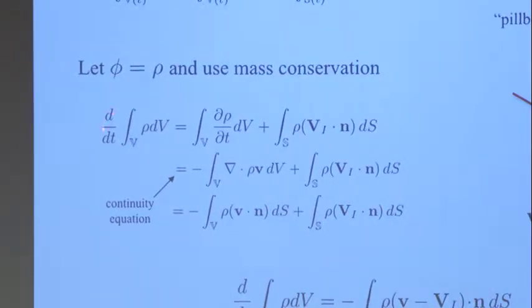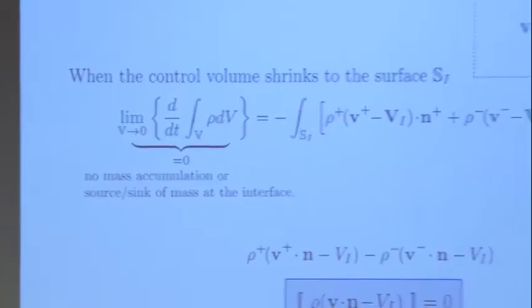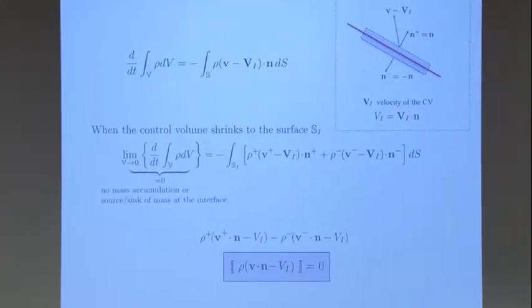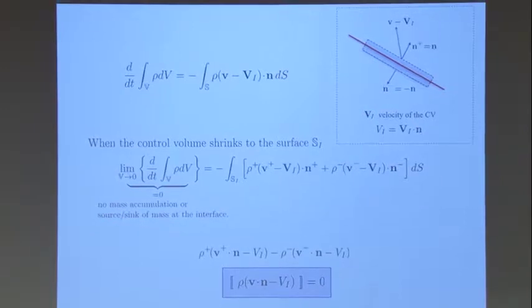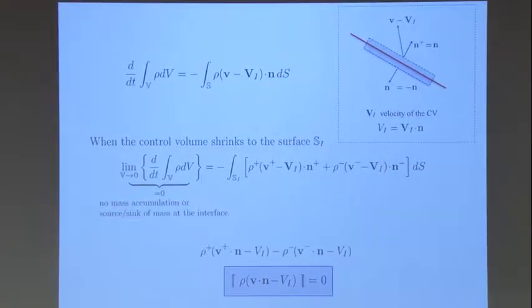And so the left-hand side, which is the time rate of change of the mass of this volume, is equal to this surface integral. Since this is what's written on top here, right? So far it's just a pure statement of mass conservation, which I manipulated in this form.